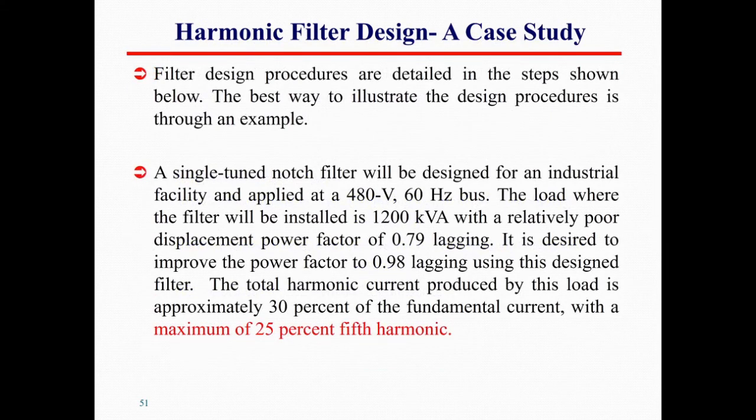Filter design and procedure are detailed in the steps shown below. Okay, so over here now we're gonna explain to you how can we design a filter. What are the steps that we need to follow if we like to design a filter? And let us start with this example. Let's say that we have single tuned notch filter will be designed for industrial facility and applied at 480 volt 60 Hertz bus.